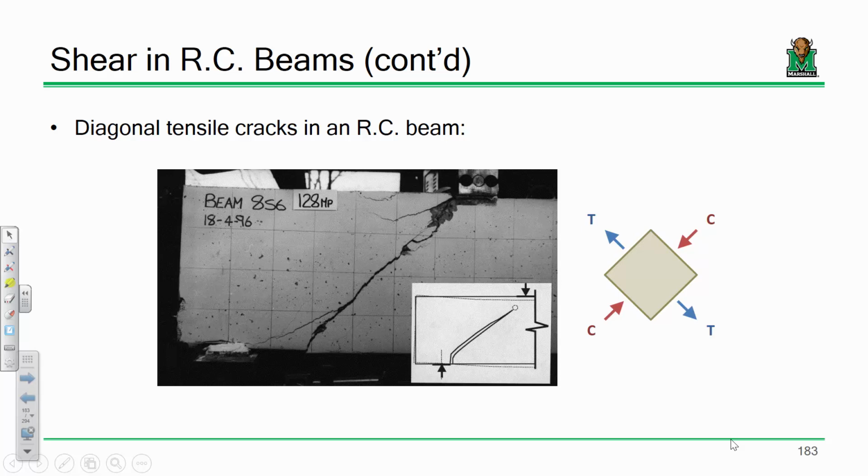But in shear, beams do not fail that way. They fail in a brittle mode. If you're ever on a construction site and you see cracks like this near the support, you get everybody the hell out of there, because when a concrete beam fails in shear, it goes quick. Okay, so that's just something to be aware of from a behavioral standpoint. If you ever watch a concrete test in shear, you see nothing, boom, it's gone.